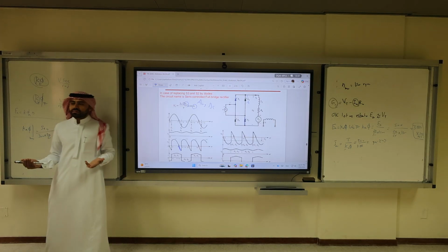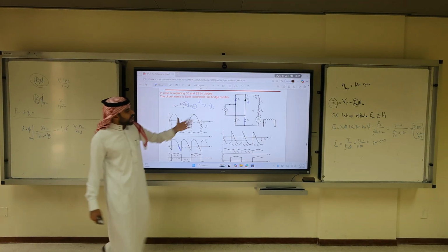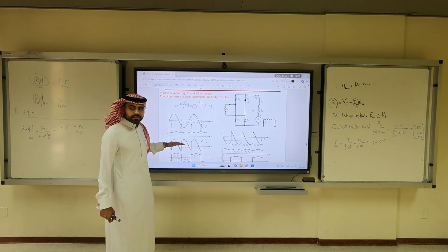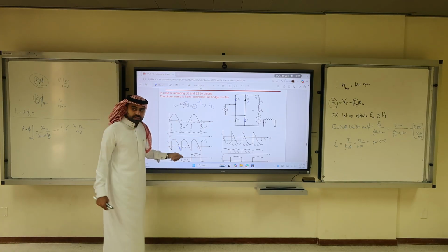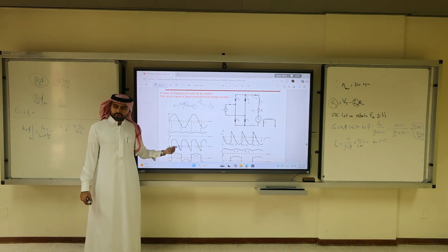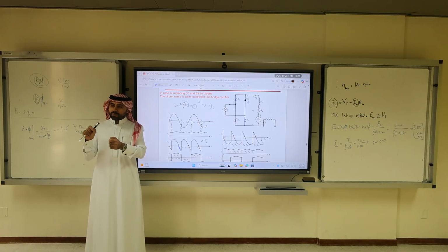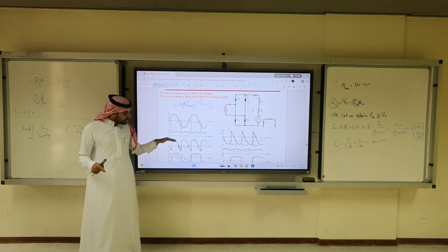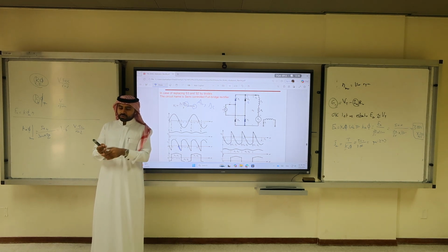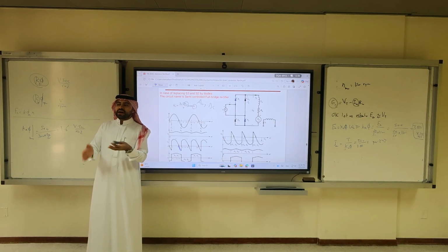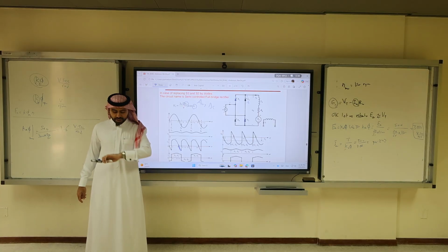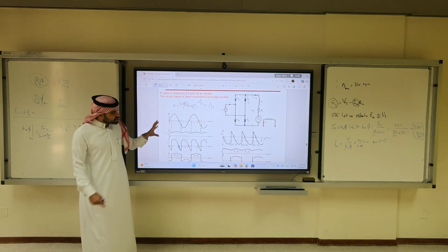So you may ask yourself, the output that I am applying is somehow chopped. It's not DC. It's not purely rectified. We look at the average. Because what will happen is at very fast frequencies from the AC supply, you're going to apply a positive DC, roughly, we can say it as DC, and then you apply a small negative. Then huge positive, small negative. So what will happen is, because the electrical constant is faster than the mechanical constant, the motor would still rotate clockwise. Okay? This is in a nutshell how it works.